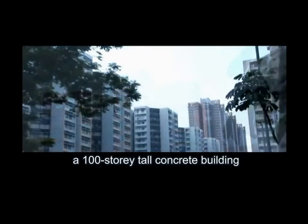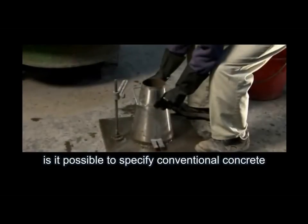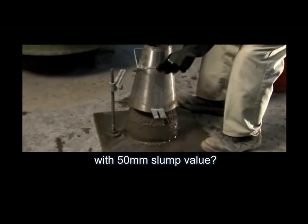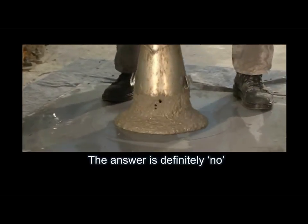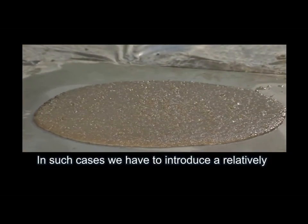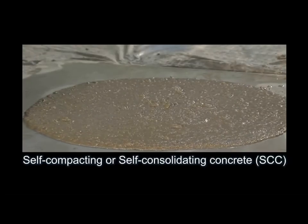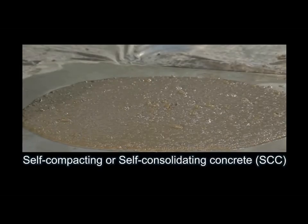As an engineer, consider that you have to construct a 100-story tall concrete building or a bridge with excellent fair-face finishes. Is it possible to specify conventional concrete with 50 mm slump value? The answer is definitely no. In such cases, we have to introduce a relatively new type of advanced concrete, self-compacting or self-consolidating concrete, SCC.